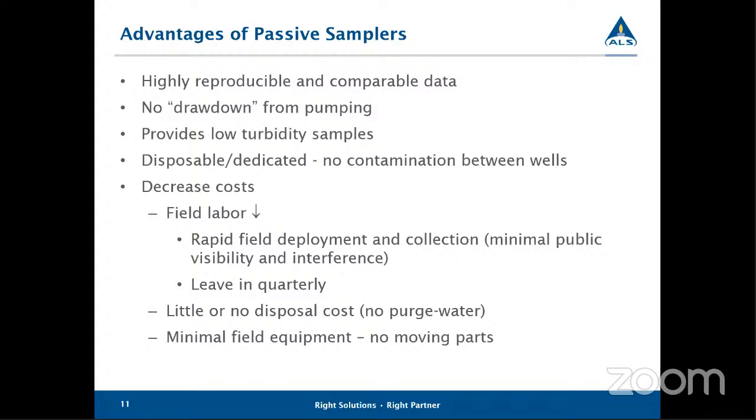But one of the big advantages here is decreased costs, mostly in the form of reduced field labor. We're talking about a matter of 5 minutes that you can go out and deploy a passive diffusion bag into a well, come back 2 weeks later, another 5 minutes to retrieve it, deploy the next one. Compare that to being out there if you're waiting for a well to refill or what have you. You could potentially be saving yourself a lot in field labor costs, time, and like it says here, minimal public